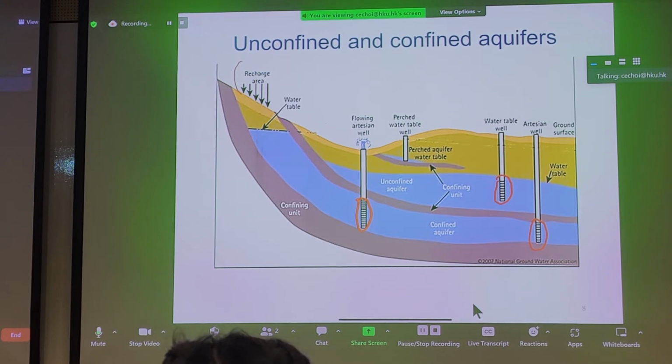You have something at a higher elevation head, essentially creating a gradient here. And the water that travels inside this piezometer would likely want to equalize to some height here. That's why you get an outflux of water at this piezometer. We often refer to this as artesian pressure.